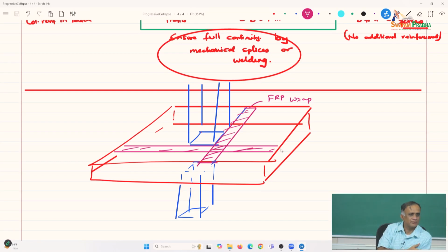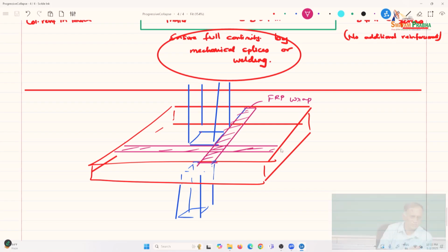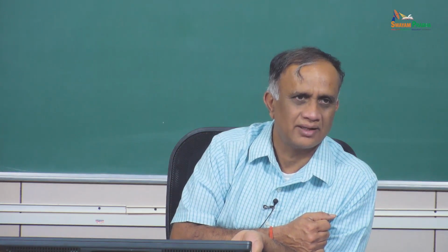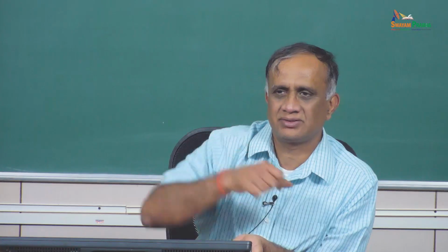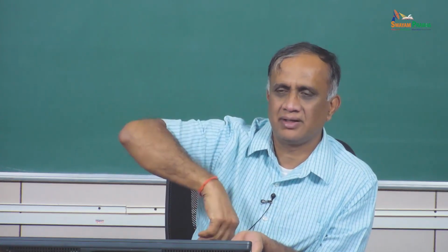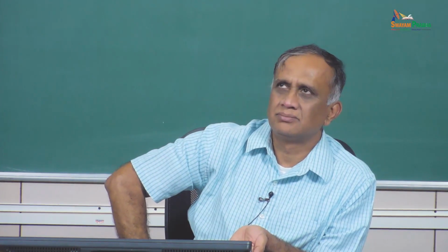Anybody else can think of or experienced anything else for strengthening with fiber reinforced? No, the normal. So you add additional concrete around it, and then yeah. It will be too expensive also. You have composite columns with steel jackets, steel enclosed around. Yeah, that will be expensive to do. Quite unnecessary. You don't need that kind of retrofit. Continuity is the most important thing.